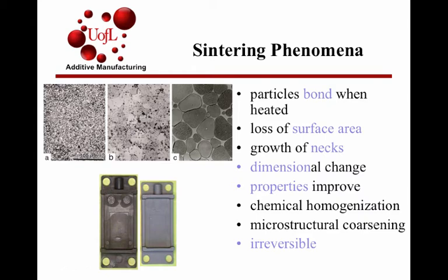If you increase the temperature beyond the melting point, of course, you will have melt pools, and they have to solidify, and so a lot of the phenomena that you have to characterize are more akin to either casting or more likely welding processes. So there are many different processing factors in sintering phenomena alone. Beyond that, for additive manufacturing, there are even more factors.